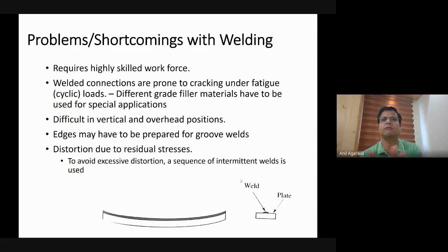But now during the welding process, in the cooling phase after the material has been deposited, the temperature control is not very good. It is simply exposed to ambient temperatures, and it cools down at different rates at different places. Sometimes it can cool down relatively faster, and as a result, you lose some of that ductility. Plus, the filler material that you are using also may not have the same level of ductility as the base metal.